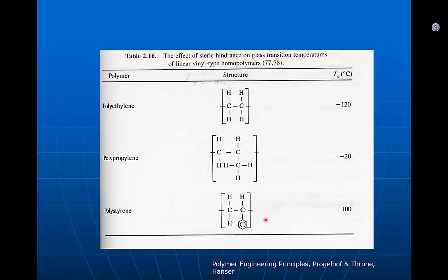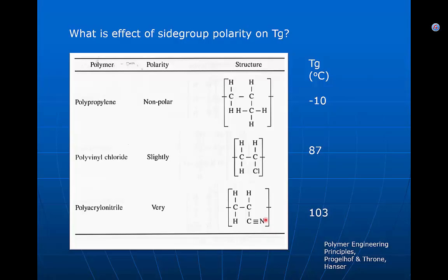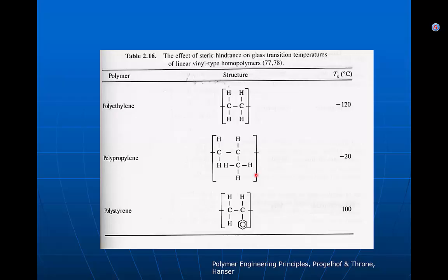So glass transition temperature, heavily influenced by the strength of the van der Waals bonds in the molecules, or between the molecules. That's another thing that this polar thing does. I can have stronger van der Waals bonds here as well, and so it's holding the molecules together, and then those negative charge centers kind of repel other charge centers, and so it restricts the motions once things get going. So kind of a dual effect. All right, so the key here is when the molecules become really mobile, we have rubber behavior, and when they're kind of locked in place, we have glassy behavior.